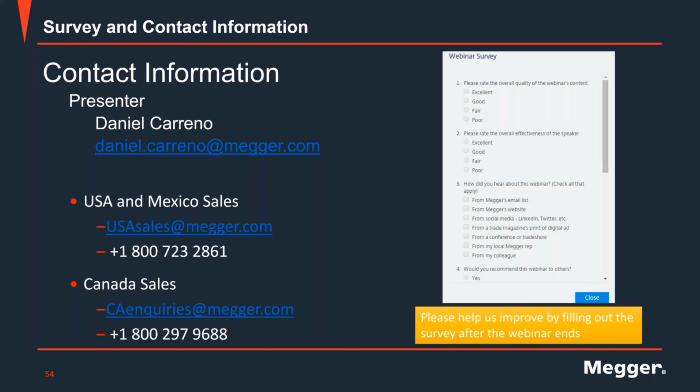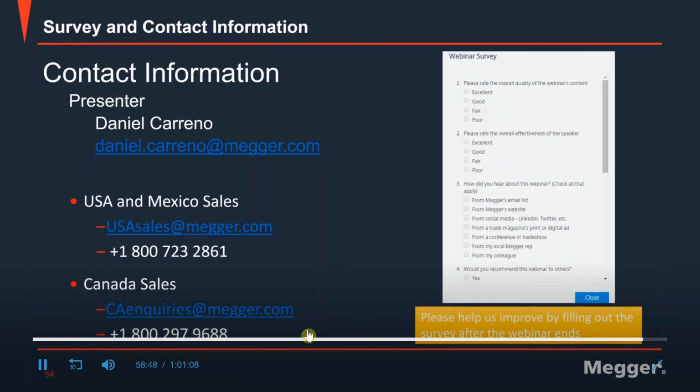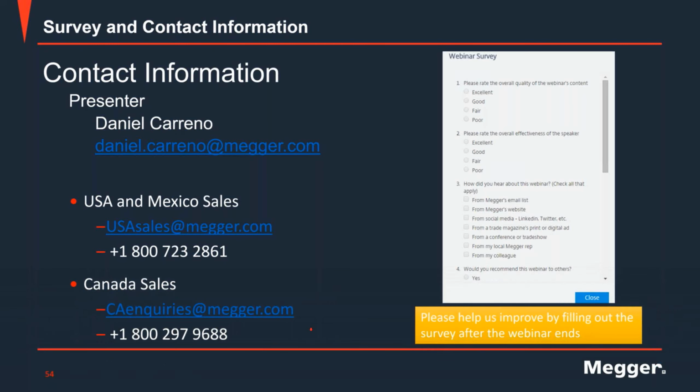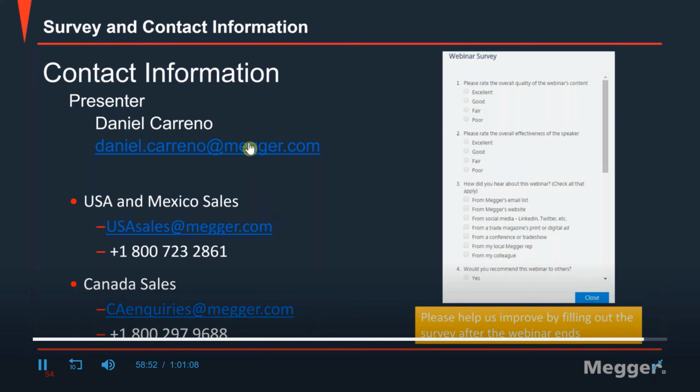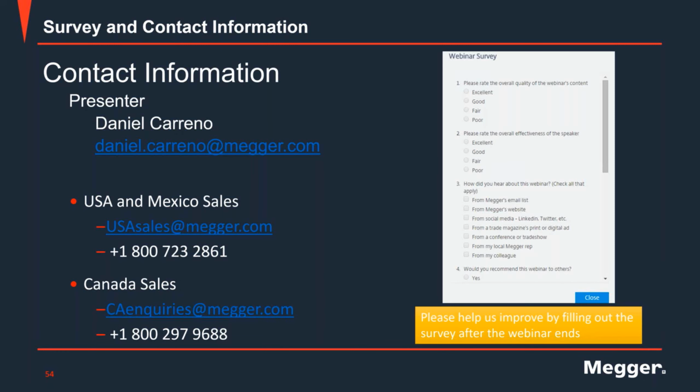All right. Also for you, Sanket, up to what percentage of error can we say that the readings are okay? What are the steps to be taken if error percentages cross that limit? So the same standard that I mentioned in the previous question, C57.12.00, states the tolerance for the ratio limits as 0.5%, and that 0.5% is with respect to the nameplate values. And that's the default limit that's set in the software as well.